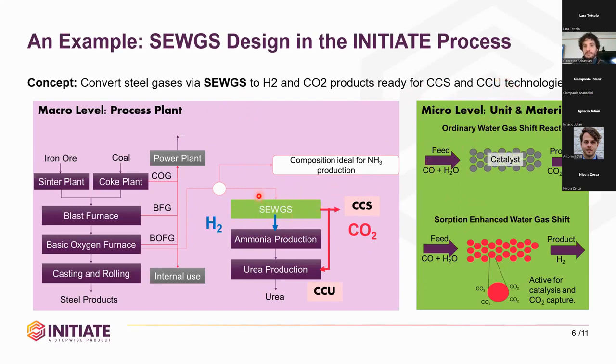And to tell you a bit more information about the CX itself, CX stands for Sorption Enhanced Water Gas Shift, and it's a catalytic sorption technology. Compared to an ordinary water gas shift reactor, there is an additional separation function added on the same material. So on the reference case situation, you would have just the conversion of carbon monoxide to CO2, and later on you will have to separate your CO2 with an additional equipment. Conversely, in the CX, we are able to convert the CO and obtain a hydrogen product while capturing the CO2 on the sorbent that can be later on regenerated and provide us with a pure CO2 stream for either CCS or CCU application.